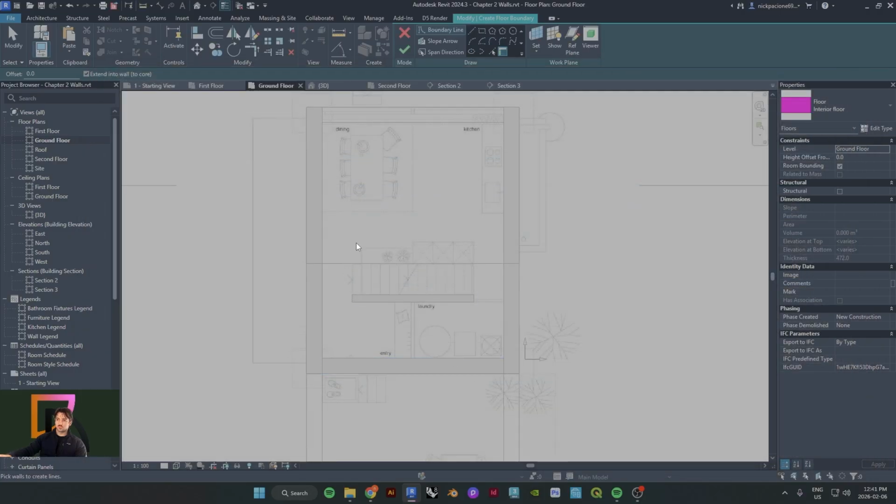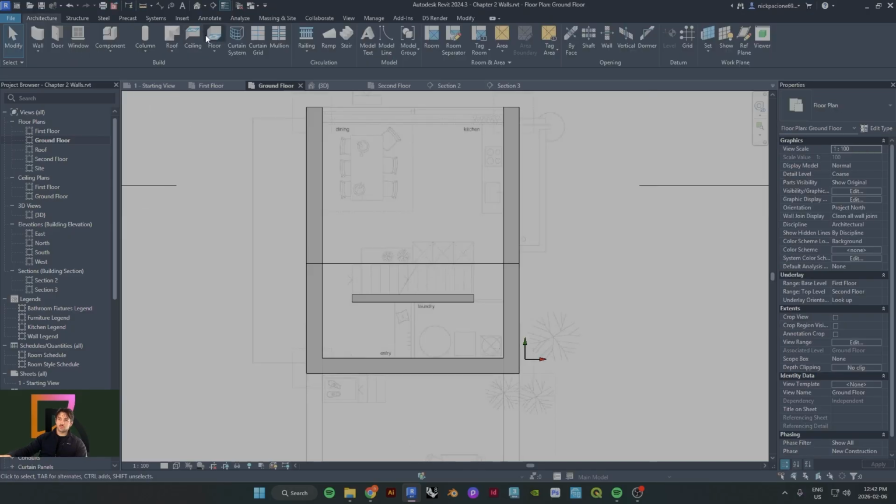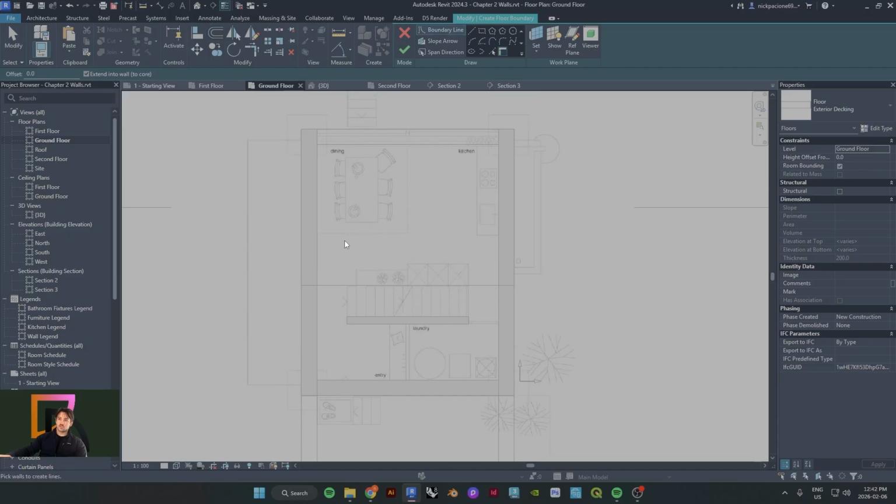So if I click OK and I come in here, I'll get out for a second. If you go back to 4, you'll notice right away everything is grayed out now. And Revit clues you in by showing you this X and this check mark. So now you're in edit mode. It wants you to sketch out in 2D where you want this floor.